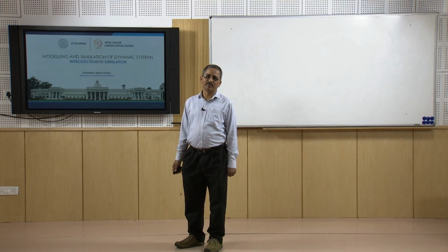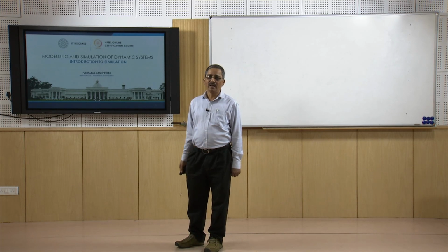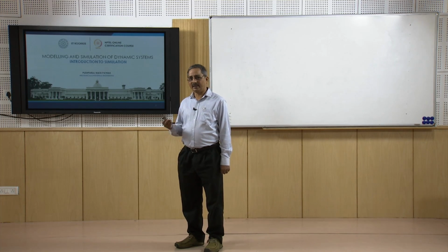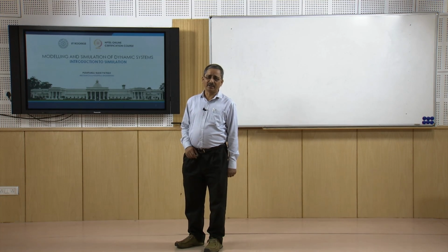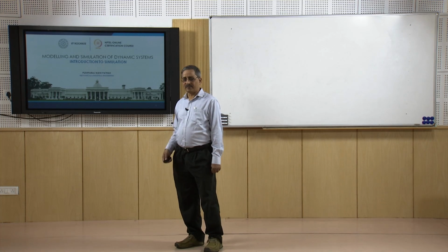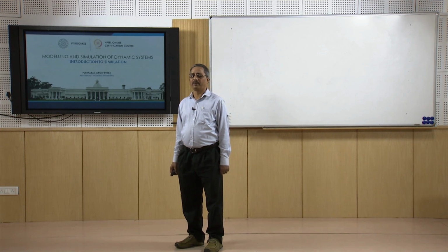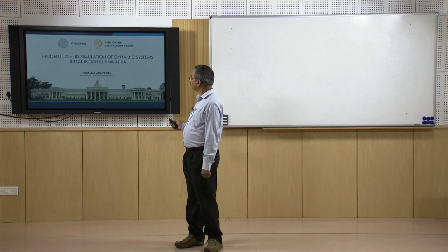So what do I mean by simulation through hardware? What people used to do is find an electrical equivalent of this simple mechanical system, consisting of a resistor, inductor and capacitor, and then do the manipulation in the equivalent electrical system in order to do the parametric study. But here, rather than experimental simulation, we will be talking about numerical simulation.